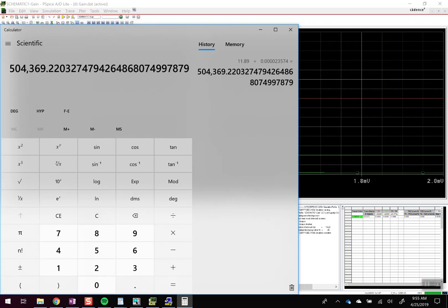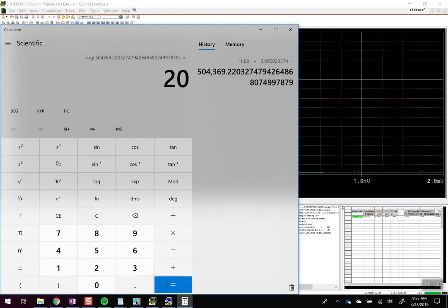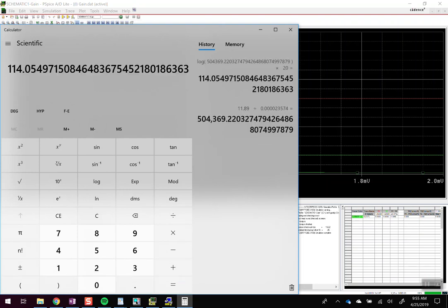Now that doesn't give me common mode rejection ratio or anything like that, and it's not the differential voltage gain in the common mode rejection. This is large signal. Remember, we had two different cases. Small signal would be looking at the differential gain if I put a small signal in there. And we can look at that too in a second. But I could also convert this to decibels, because in some data sheets you'll see the large signal voltage gain reported in decibels, and in this case it would be 114 decibels.